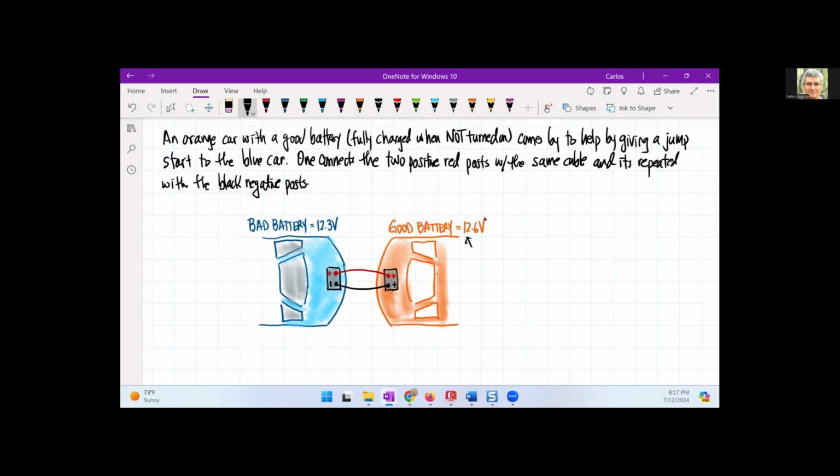What we do here is that they ask you to turn on the car. That increases the voltage to 13.8 to 14.2 volts. And even if you rev it up, you bring in the alternator, which even kicks that even higher. But that's the reason why you want to turn on the car so you can get that higher voltage.